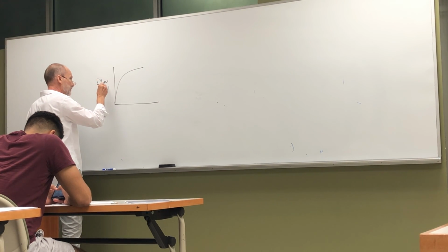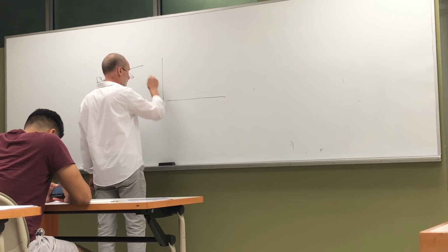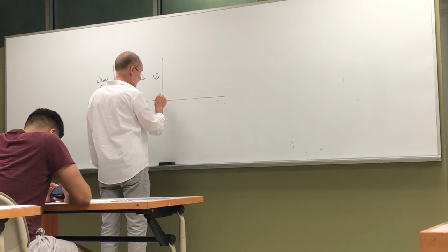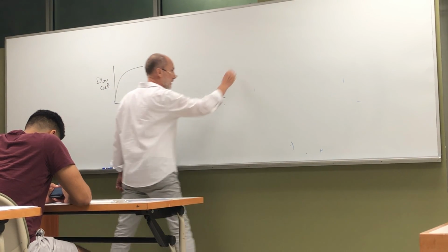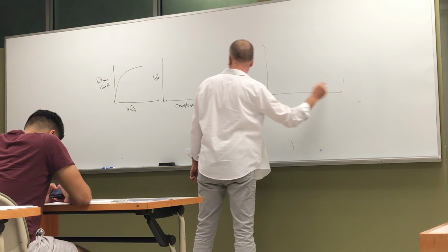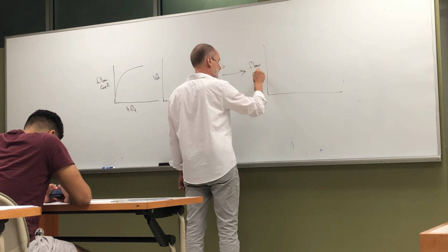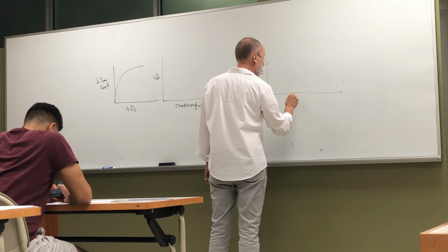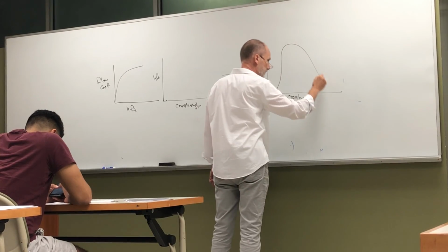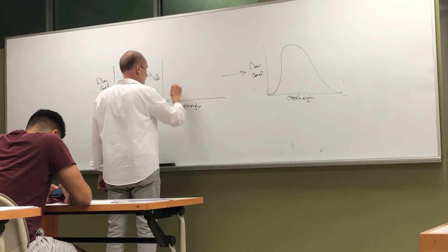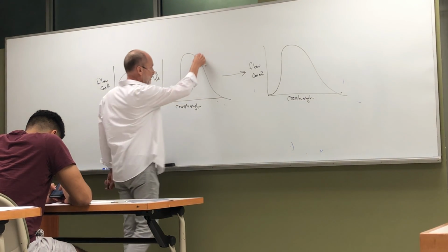Flow coefficient. This is lift. Lift versus crank angle. Now I make a plot of flow coefficient versus crank angle. And I end up with something that looks like this, because this looks like this. And as we go to higher lifts, this just exaggerates the shape of this.